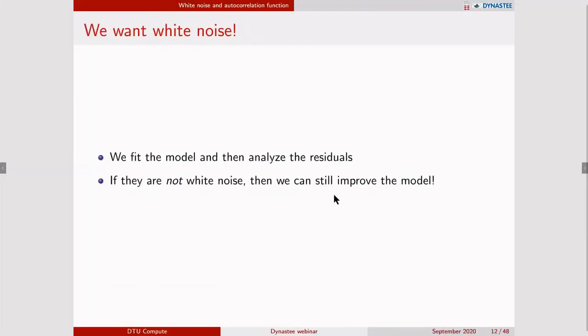Because that's what we're going to use when we fit models to data. Then we want to validate the model. We want to analyze the residuals, and we want to check if they are white noise. If they're white noise, we're happy. If they are not white noise, well, then we know we can still improve the model.